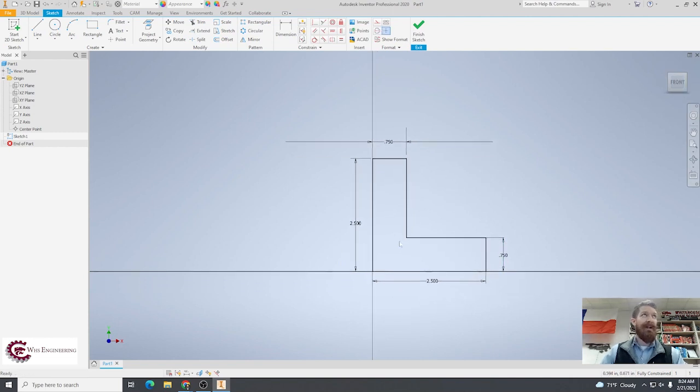You're in sketch mode right now, so as soon as we're done with sketch mode and we extrude, these dimensions are going to go away. The visibility is going to be turned off, but they're still there. Notice how all the lines changed from blue to black. This is very important. If you leave something unconstrained, you'll have a blue or a purple line. That means it's not fully locked in. In other words, I could take this line and move it freely. It's not constrained. So make sure before you extrude, all of your lines should turn black. All of these lines are black. That means they're fully constrained.